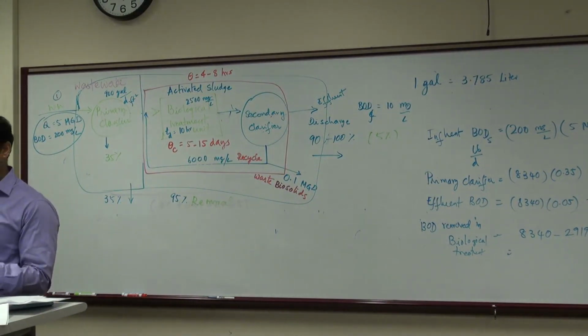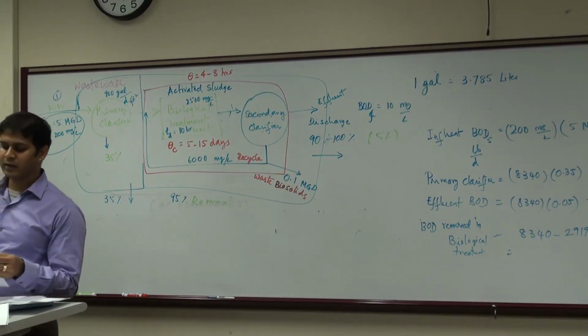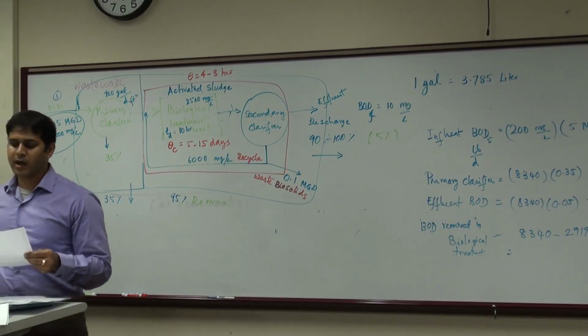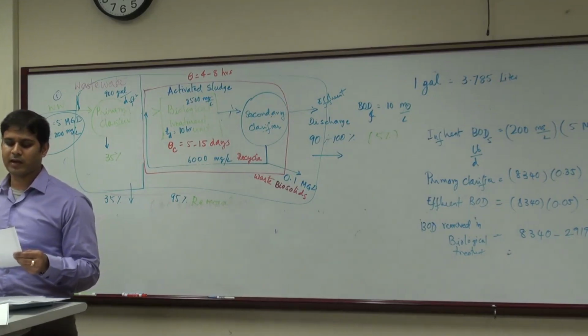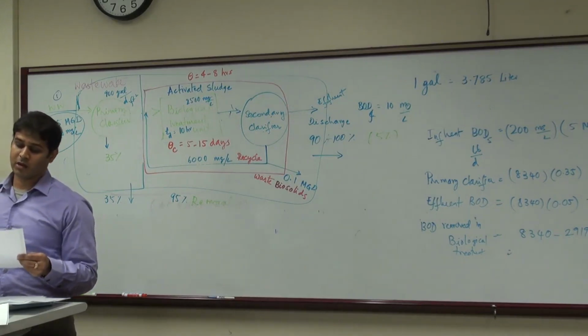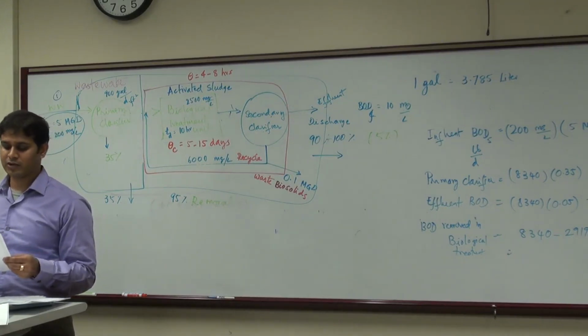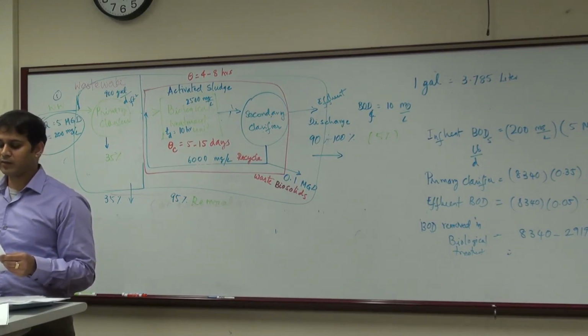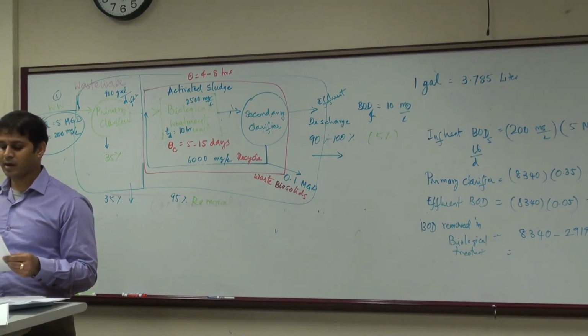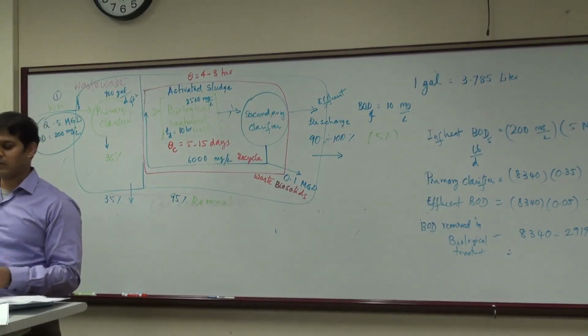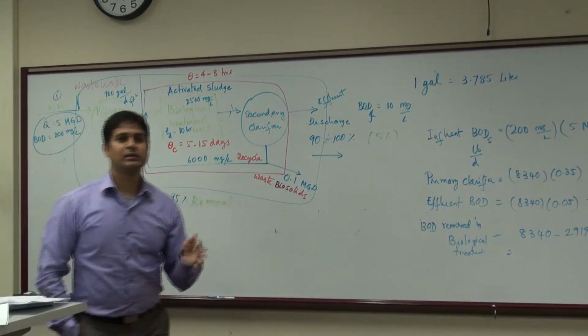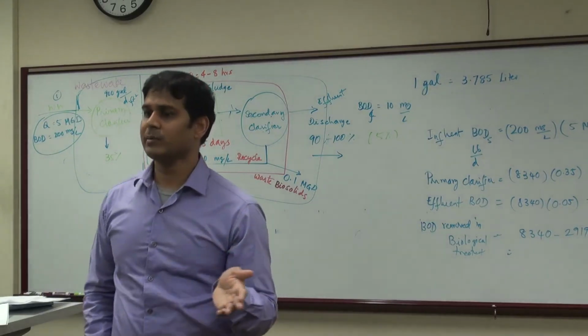You are designing an aerobic system to biodegrade benzene. The biodegradation follows the chemical reaction below. You've been given the molecular weights, and the benzene concentration is 500 milligrams per liter. The amount of oxygen that will be consumed to completely biodegrade the benzene is most nearly... It's nothing but the concept of theoretical oxygen demand calculations.